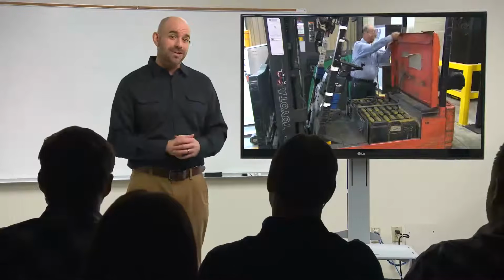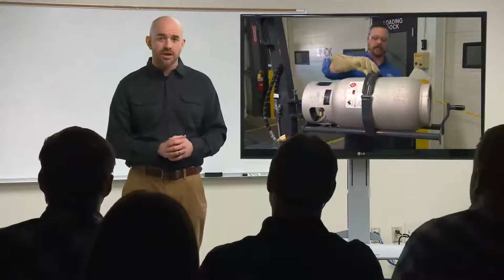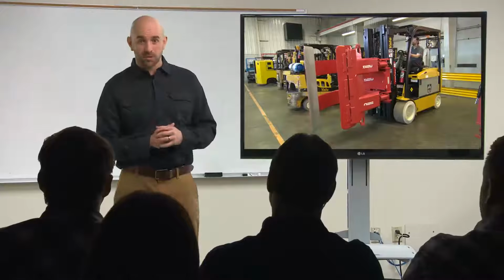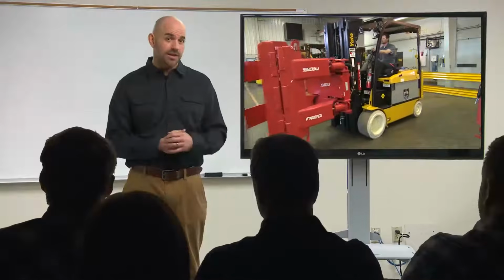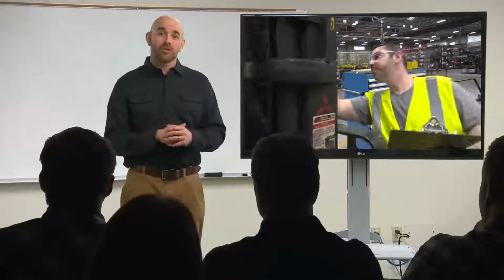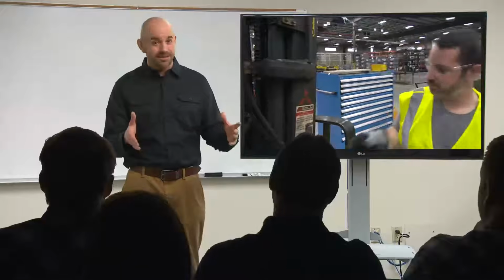Make sure you understand how to safely recharge or refuel the forklifts you're authorized to operate. Only install attachments or modifications if they are approved and the lift's capacity is updated. And take a proactive role in the maintenance of your forklift, reporting defects before they become deadly hazards.